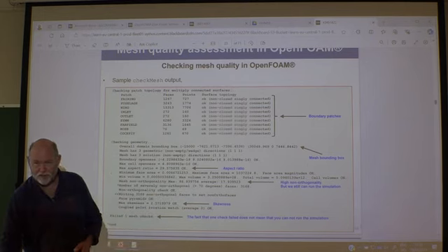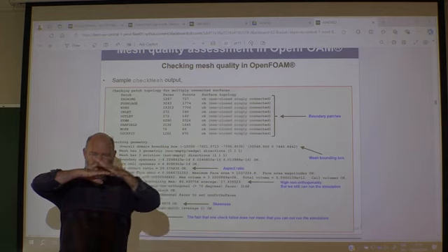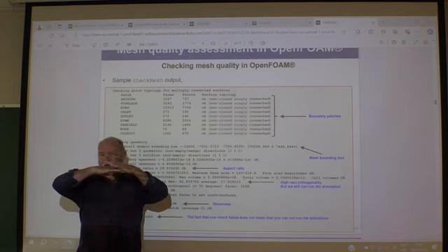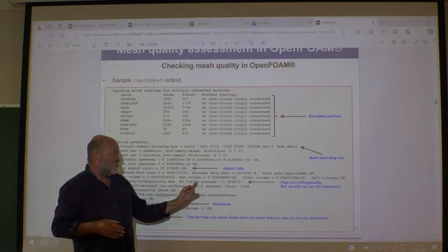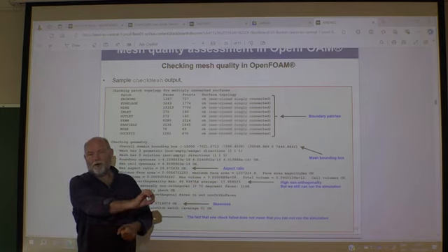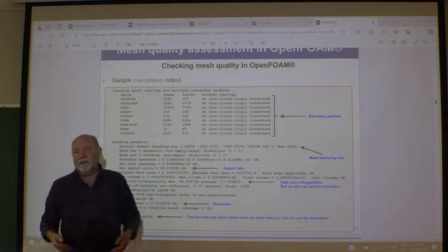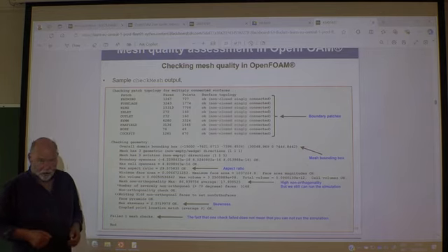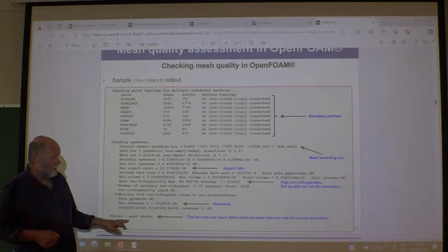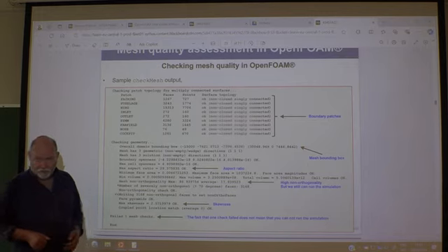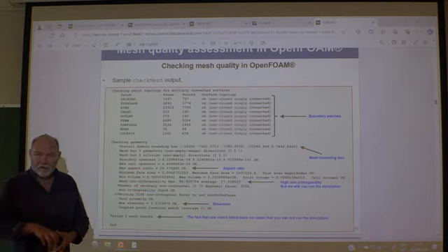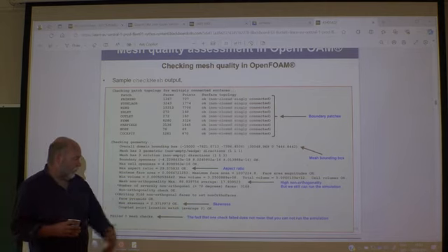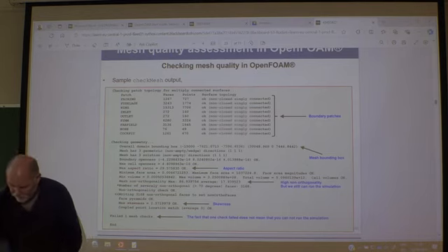That is a cell that has an angle of, what is it, 90 minus 87, that's 3 degrees. It's fairly thin. But if this is just one cell in one unimportant region in your domain, it may still run. So although the check fails, it can still be okay. So don't take it personally when it says fail, you are stupid. It doesn't really mean it. Okay? Skewness, 2.5, that's okay.